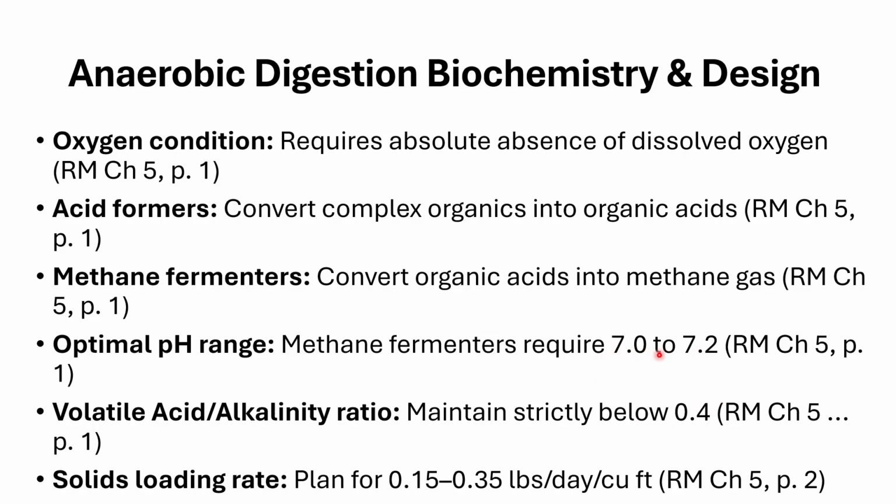If these two vary, these are symptoms that we're going to have something called a digester upset that we'll talk about. The volatile acid to alkalinity ratio is the quickest way and the precursor. This is the first symptom you're going to see. The pH is a follow-on symptom of a digester upset, but we'll talk about that in a couple of slides. Okay.